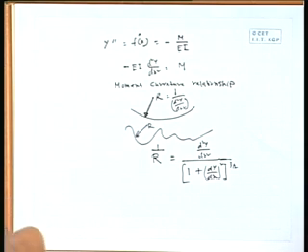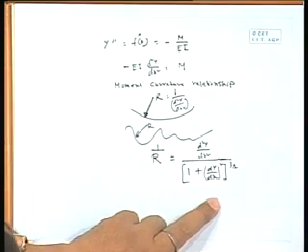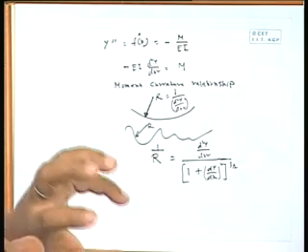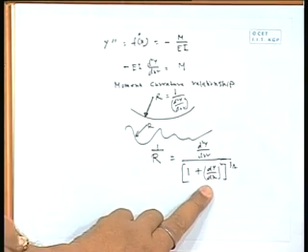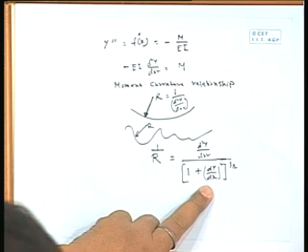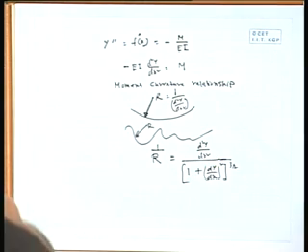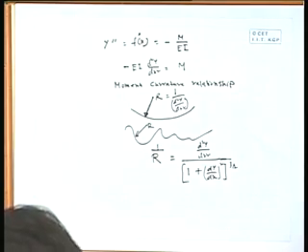But here we are not taking the denominator part. The reason is very simple: we will be dealing with structural problems, and in structural problems deformation will not be very large, it will be very small. When deformation is small, its rate of change, the slope dy by dx, will be much smaller, and the square of that will be even smaller. So this quantity will practically be 0 and we can neglect it. The denominator will be 1 to the power 3 by 2, which is basically 1.